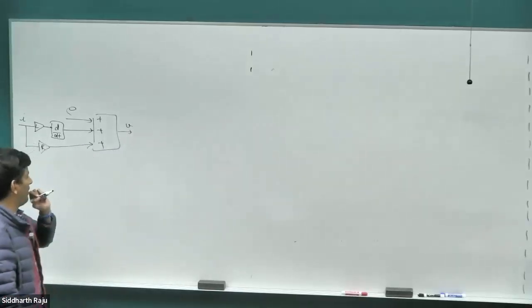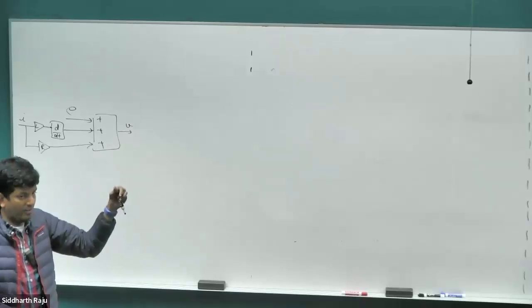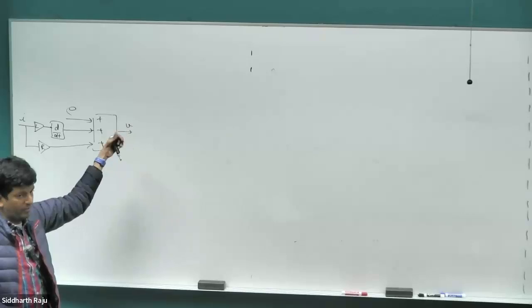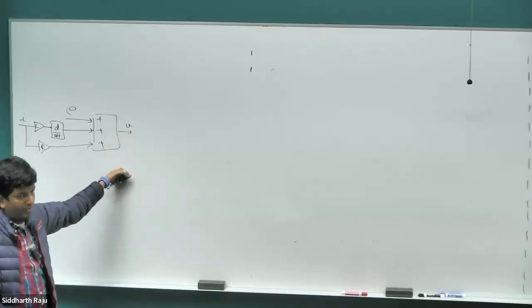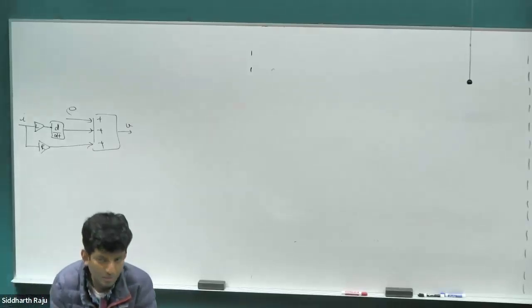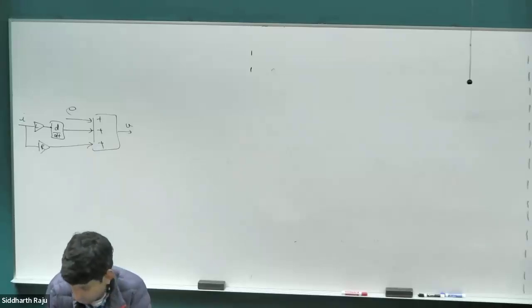That's a very good answer. The only problem is voltage is the input to the system. Voltage is something I have given. But through this diagram, you are giving me a voltage which would not match the voltage that I've given, which is not going to give me a solution. So how do I flip the system so that the voltage is the input? How do I restructure it so that the voltage is the input?